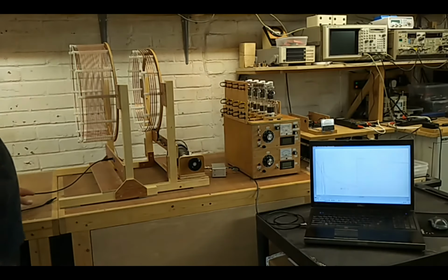So then we're working with a lower impedance at the bottom and a higher impedance at the top end, so we're looking to resonate that in quarter wave mode. That'll make it a quarter wave resonator, as we would expect to use within normal parameters and within the type of experiments that we're going to do with this kind of coil. So I think that's everything about the setup. It just gives an overall idea of how everything's connected.